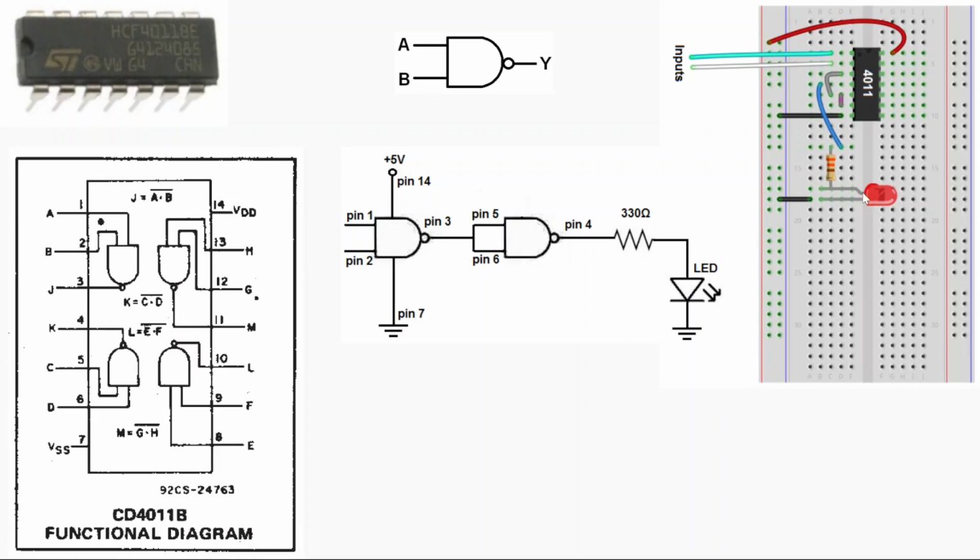As you can see here, even the longer leg indicates that it's the positive side, but some LEDs do have these notches, because we do cut the legs to make them equal, for numerous purposes. But still, you can find out from this little curve which side is the positive side of the LED. So we're connecting the positive side with the other end of the resistor, and the negative side goes to the ground.